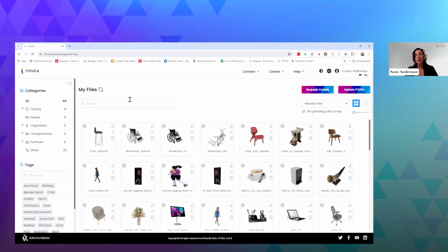So it looks like we do have a question. The question is, how do I get the Revit plugin? So the Revit plugin is available from the download section of our website. If you want the full experience for using, let's say, RPC assets inside of Revit, you'll want to also download AVAIL and the AVAIL plugin for Revit.